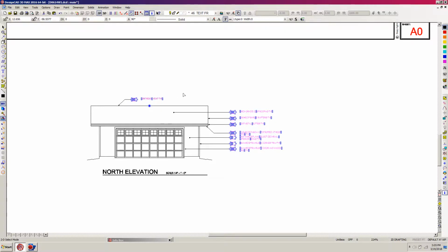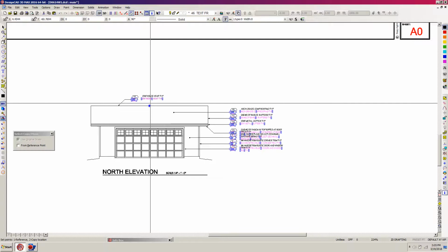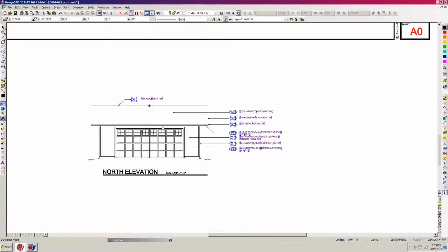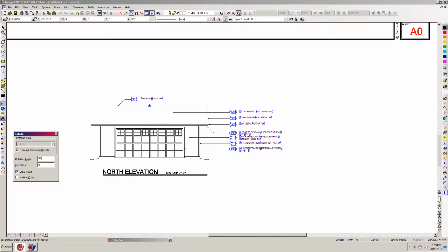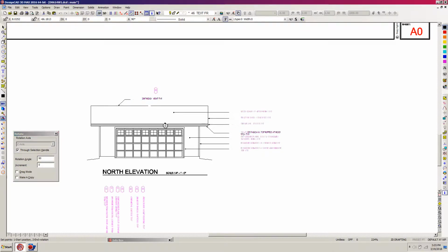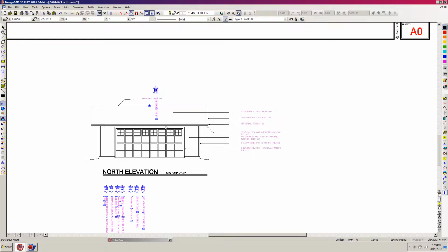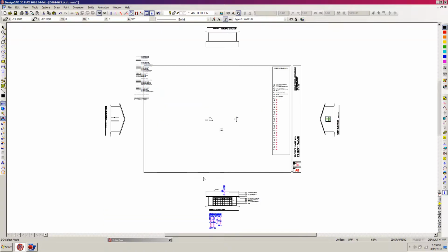I'm going to hit N to duplicate all of this, N, and then right click to my handle. So now I have one set of notes on top of another set. Now I'm going to hit R for rotate, R, and then tab, and then type in 90 for the rotation angle, and hit enter. And so now I'm going to hit Control W, and you can see now that we've rotated about that handle, and you see my other sheet notes are still there.